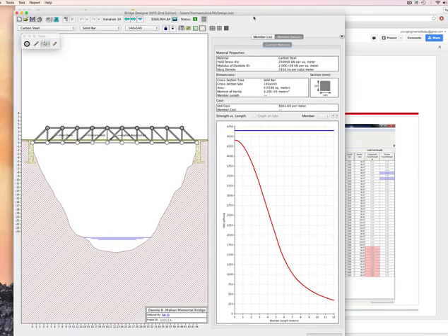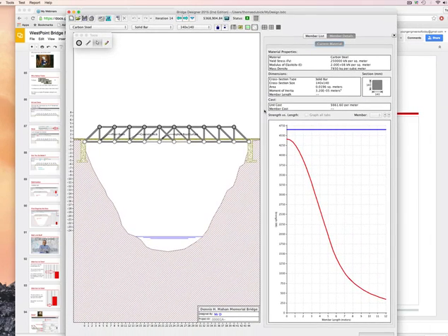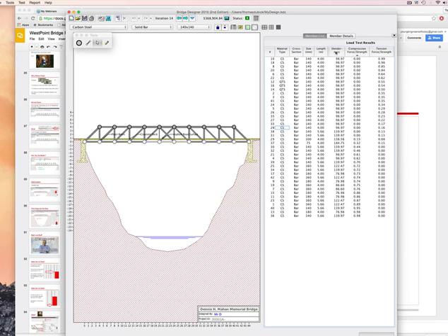All right, now, so I'm going to take this. I'll go back to my member list. I'm looking at my costs. I'm at 368. What I'm going to do is go, well, look at all these, and I might concentrate on compression or tension, pick one or the other, doesn't matter. And I might go, okay, I'm going to get all my compression ones as close to one as I can, but I don't want them to go over one. That generally is cheap, as a way to make it cheaper.